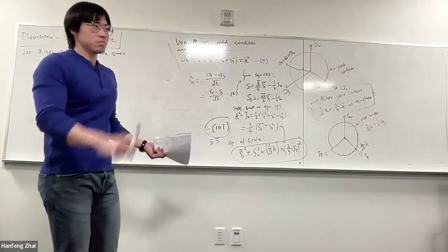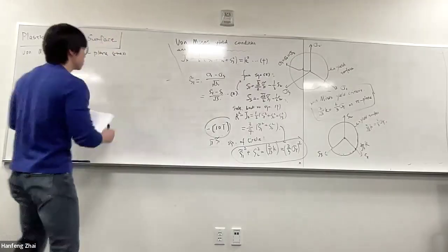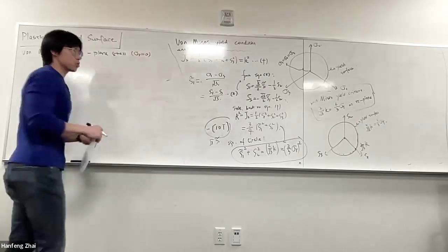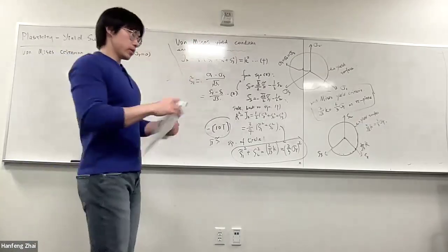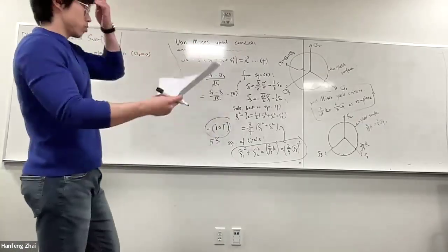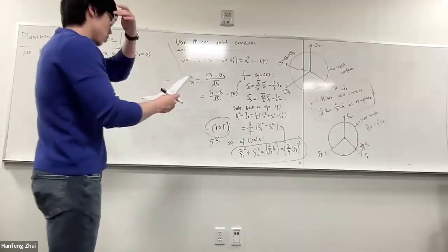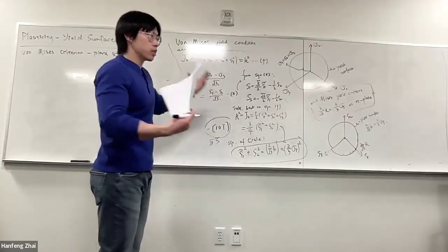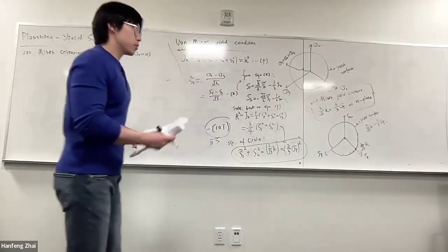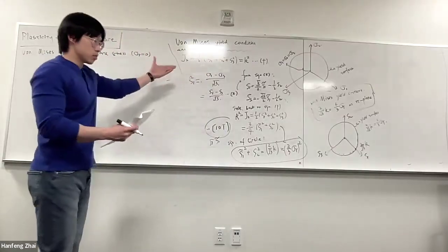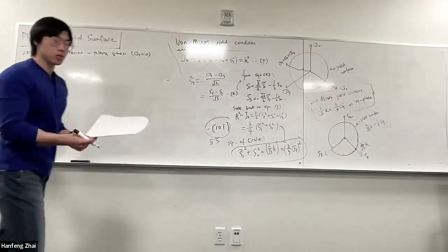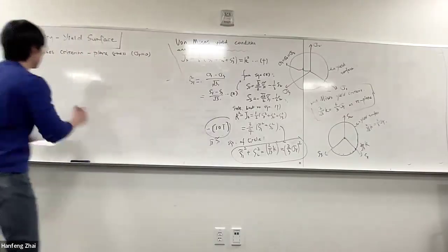Sigma 3 equals 0. The third principal stress component is 0, because there's no stress in the z direction. And correspondingly, the third principal stress also goes to 0. We already know this is a definition, or by construction. This is how the Mises criteria is defined. So we just literally substitute into the equation for J2, right?